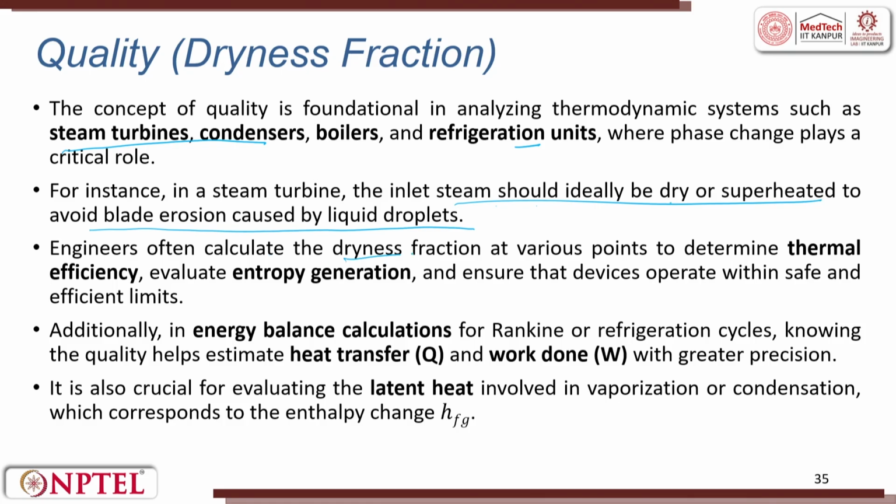Engineers often calculate the dryness fraction at various points to determine the thermal efficiency and the entropy generation. Additionally, in energy balance calculations, as we will see in the Rankine cycle and refrigeration cycle, knowing the quality helps us to find out what the heat transfer is and what the work done is. So, for energy balance, heat transfer, work done, everywhere in the PV diagram, TS diagram, the dryness comes into existence. And dryness, you know that it is 25%, 50%, 75%, you can try to define.